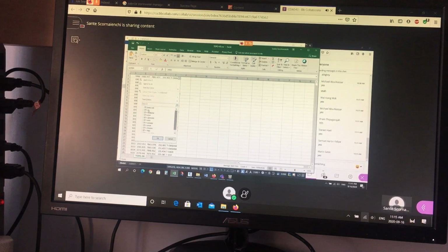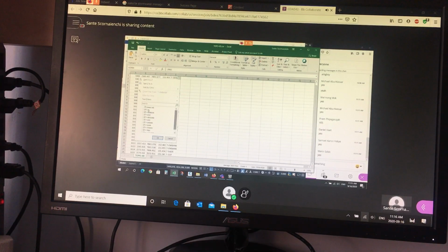Right? So you could have a description key for different companies. Survey company ABC has this description. Well, let's program it once and for all, so that when we get their stuff, we can import it quickly into a drawing and make sure that everything's on our layers, so we have our standard. Company QXR, they have a different naming convention for their descriptions. Okay, so I'll create a description key for that company so that I can import their descriptions onto our layers, and so on. So you could always create a standard drawing for your company from various sources. Okay, so that's the point of this.